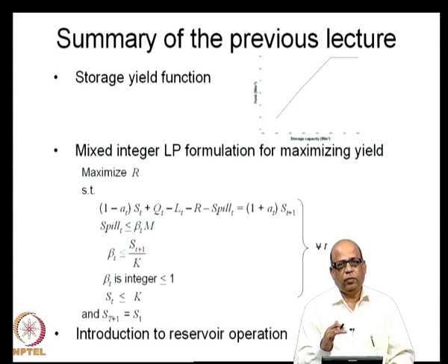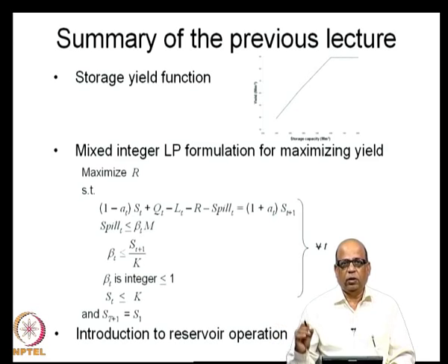Now, the state of the system can be storage alone, or storage and inflow together, or storage, inflow and rainfall in the command area, storage, inflow, rainfall and soil moisture in the command area, etc. So, as much sophistication as desired can be put into these models. So, that is what we defined as reservoir operating policy. And the simplest of such reservoir operating policies, which is commonly adopted intuitively in most of the reservoirs, especially in India, is the so called standard operating policy.